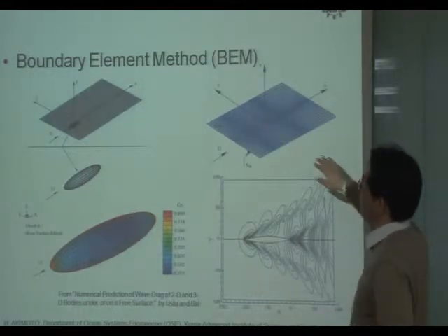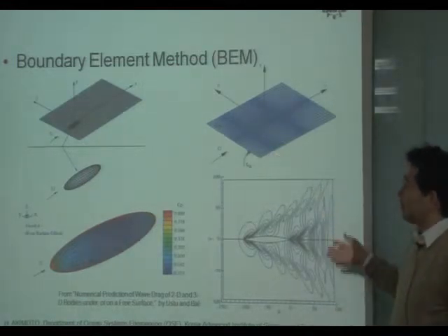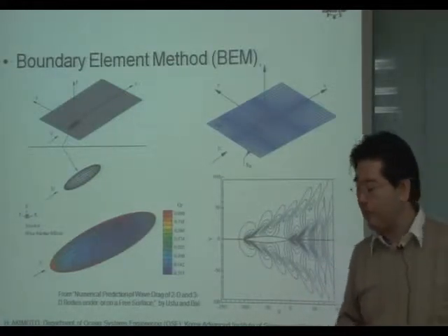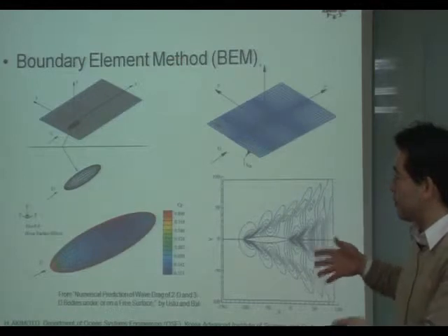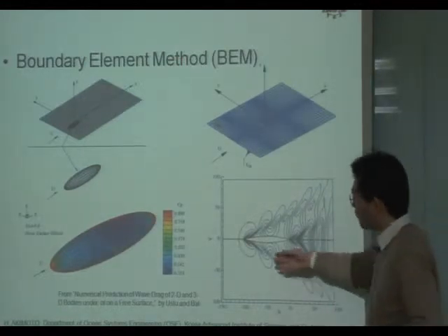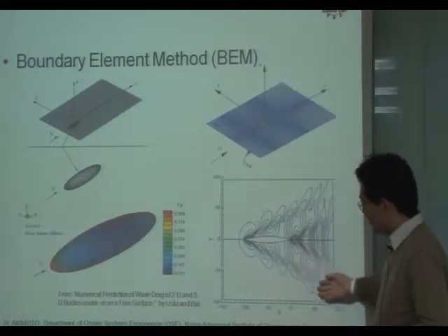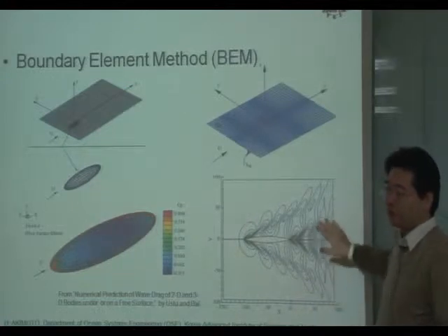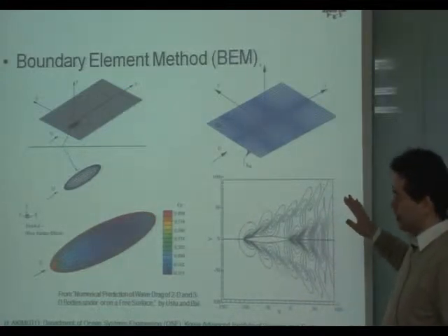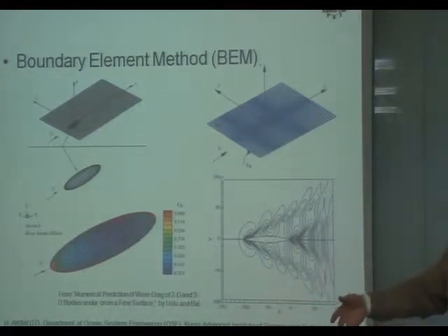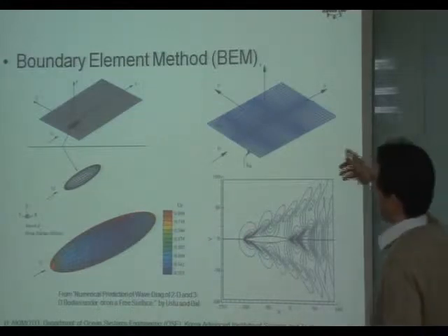But in the boundary element method, it does not have any diffusive capability in the system of equations. So the wave pattern is very clear even far from the body surface. So if you want to know the clear wave pattern far from the ship surface, boundary element method is a good choice.